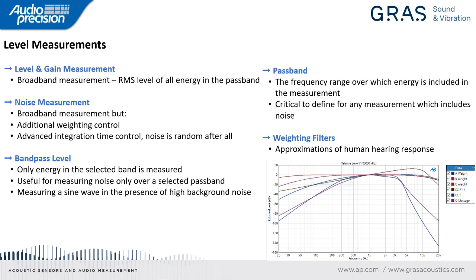And we describe this as a broadband measurement. So it measures all the energy in the currently defined instrument passband. So it measures both your fundamental, any noise, any distortion, all of that gets added together, and you just get one result. If that's what we want, that's great. But sometimes we're looking for peculiar things.